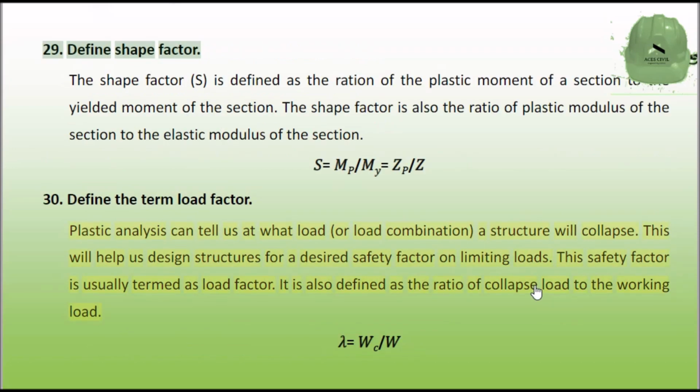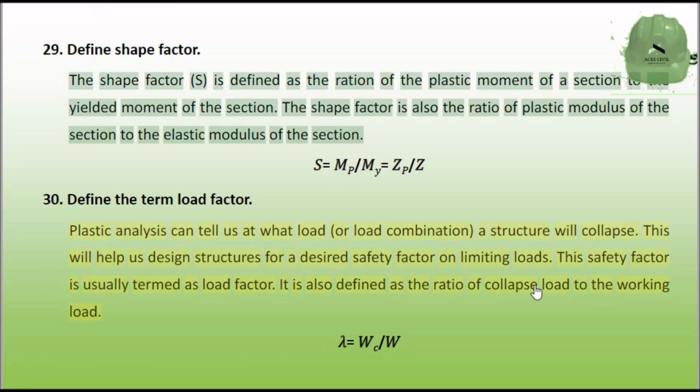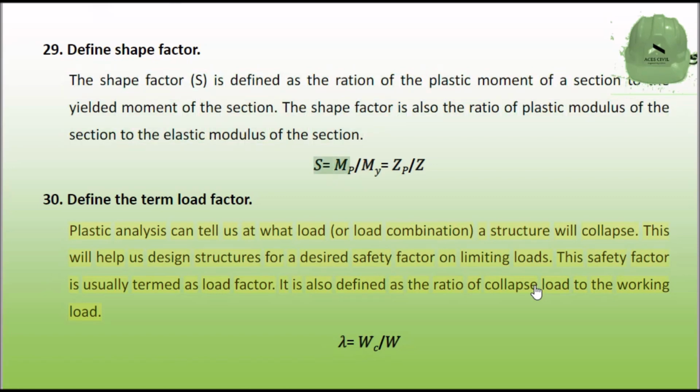Define shape factor. The shape factor, S, is defined as the ratio of the plastic moment of a section to the yield moment of the section. The shape factor is also the ratio of plastic modulus of the section to the elastic modulus of the section.